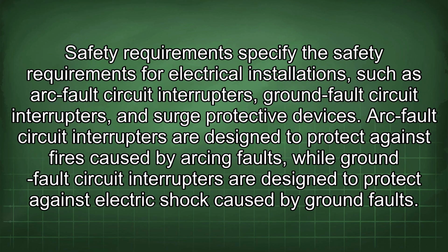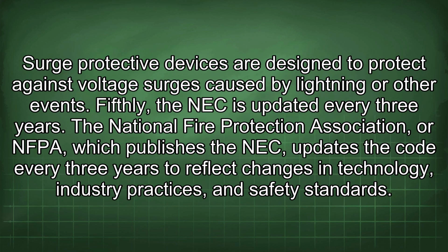Safety requirements specify the safety requirements for electrical installations such as arc fault circuit interrupters, ground fault circuit interrupters, and surge protective devices. Arc fault circuit interrupters are designed to protect against fires caused by arcing faults, while ground fault circuit interrupters are designed to protect against electric shock caused by ground faults. Surge protective devices are designed to protect against voltage surges caused by lightning or other events.